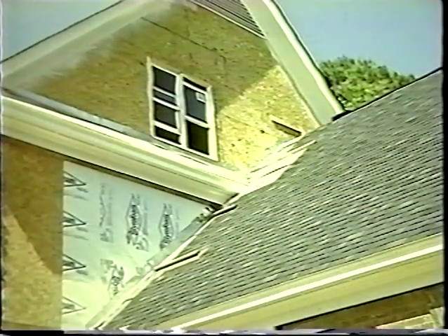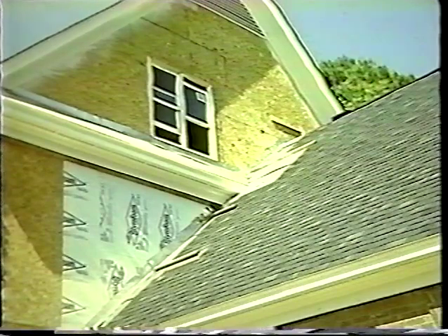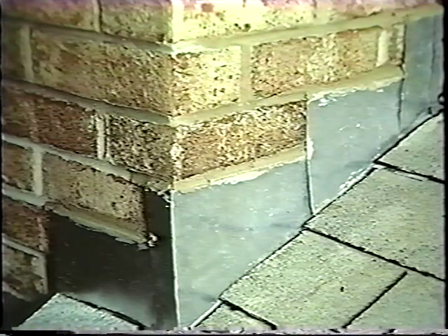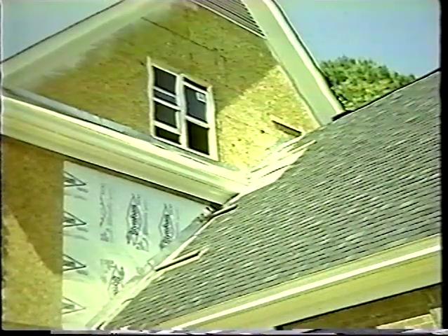Where roofs and walls or chimneys intersect, through-wall flashing and counter flashing must be installed properly to avoid the damage of water penetration, as you see here. Through-the-wall flashing is necessary to direct water that has penetrated the wall above the roof back out again. The roof counter flashing is not sufficient to stop water that runs down the interior face of the brick. Through-the-wall flashing will force the water out through the weep holes.